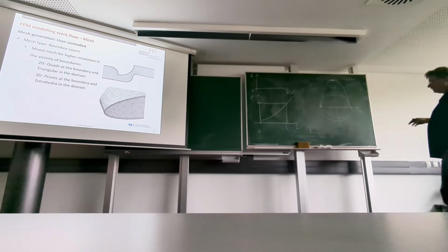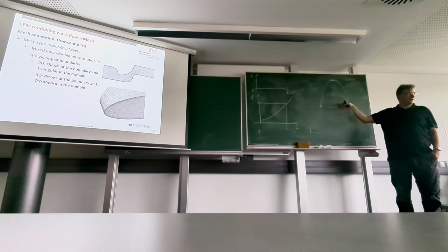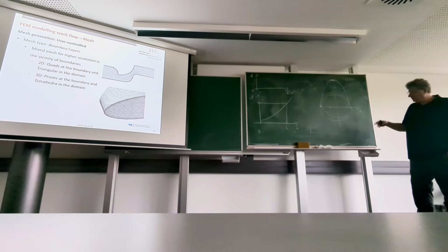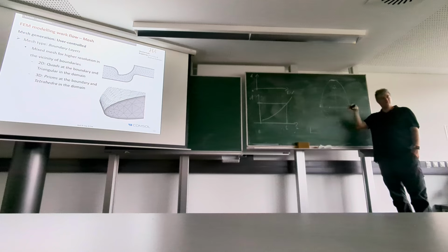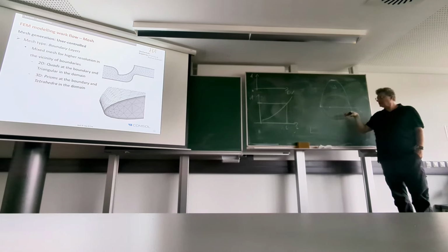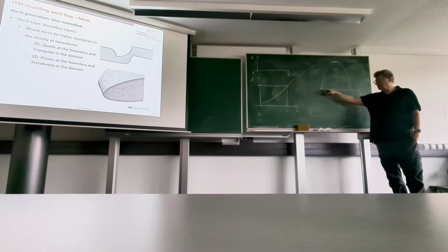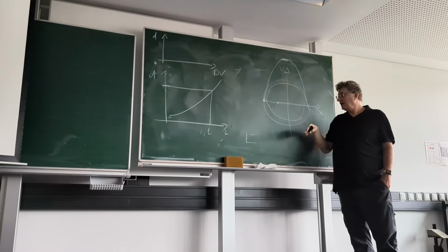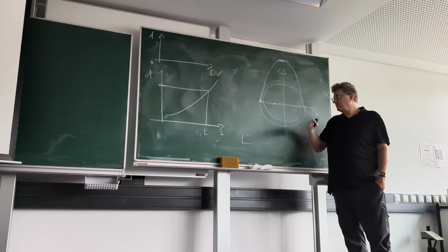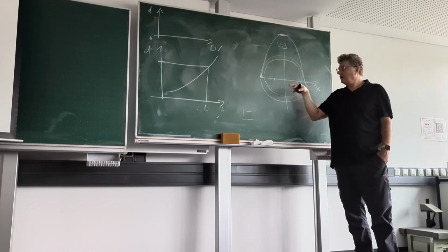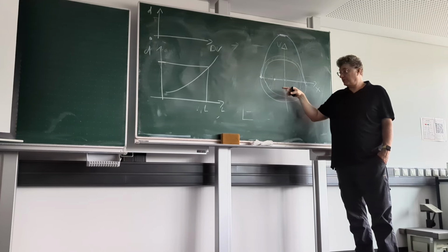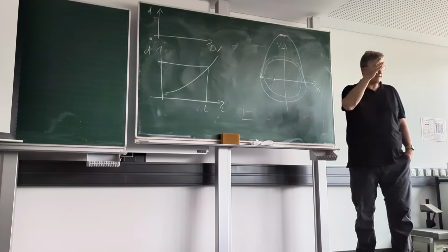In the skin effect, you also have such a cross section. In simple case, just a circle. If you let the current flow through that cross section, how the current is flowing depends on the frequency of that current. So if it's DC, it's flowing equally. There's no reason to flow different in the middle from the boundary, so it's different from fluid, obviously. But if you increase the frequency, means let the current flow in, let the current flow out, and switch back and forth, then at a certain frequency, the current actually starts flowing on the boundary, on the skin. That's why it's called the skin effect.